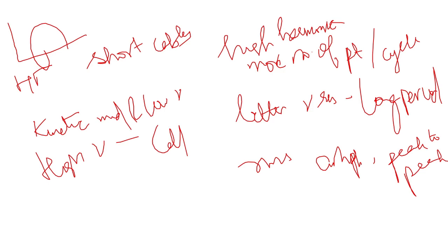So if the input waves are harmonic, we will get fewer points per decade, and if the input waves are not harmonic, we will have longer acquisition time to reduce the aliasing effect and spectral leakage effect. So these were a few of the points, and we also saw windowing, etc. in the second week. Then we come to getting an impedance response.